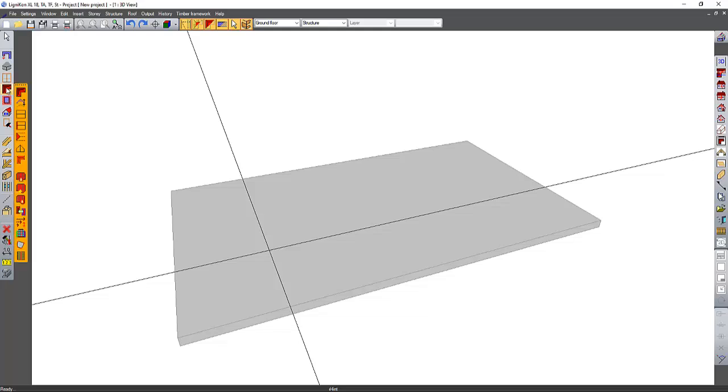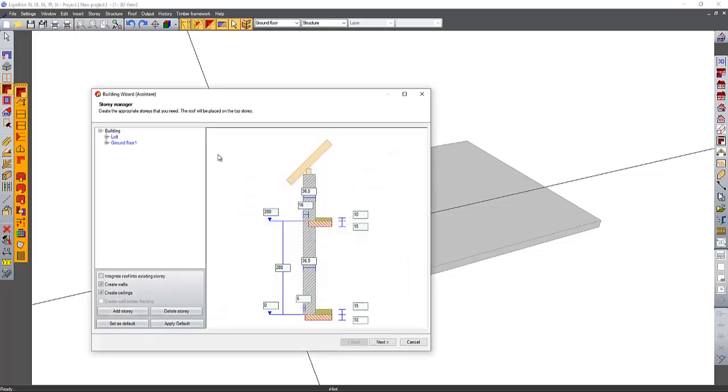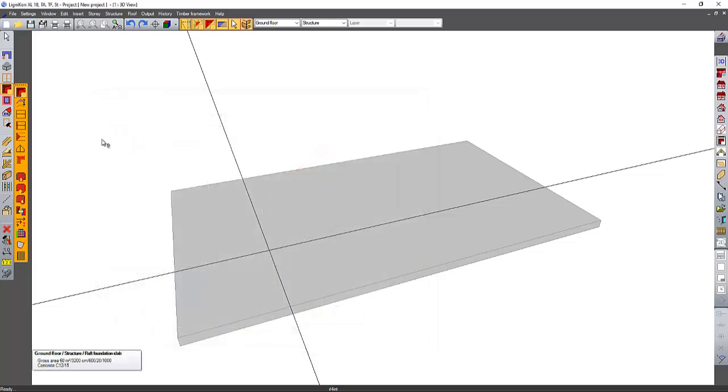We go to the roof tools. The first button is the width, which we have already seen in the previous video, so we will not use it. The second button is to edit an existing roof. We will use this often because sometimes you have to fix something. Then we will see the button to draw.